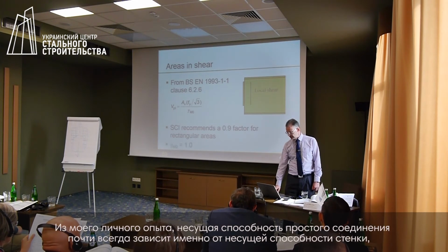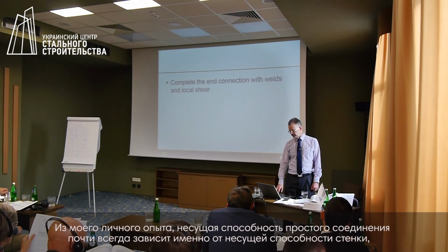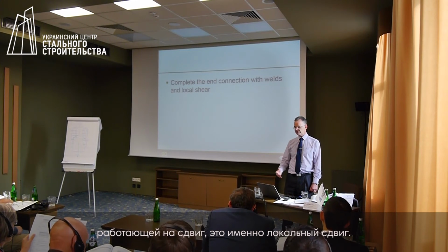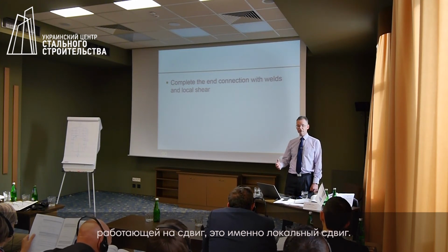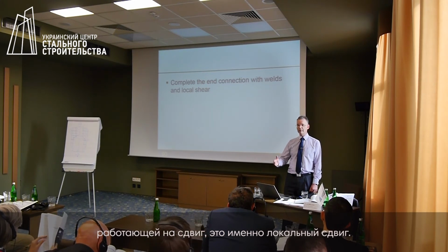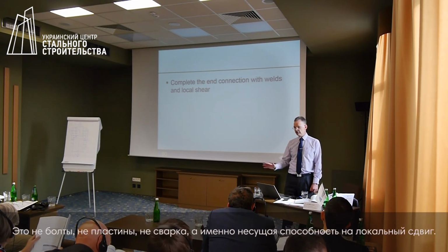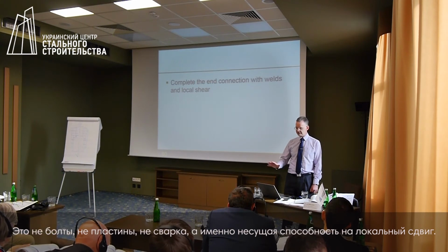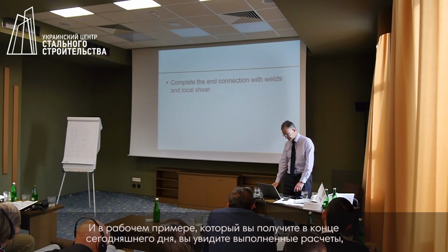Now, in my experience, the resistance of a simple connection, I'm not going to ask you to do this worked example, the resistance of a simple connection is almost always dominated by the resistance of the web in shear. Not the bolts, not the plate, not the welds, but the local resistance.